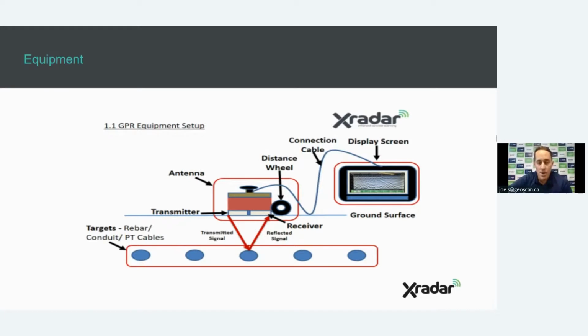Effectively, it works by the radar passing through the concrete, and as there's a change in material from concrete to, say, steel, such as reinforcing, it causes a reflection back up to the receiving antenna that displays that reflection on the screen. And so a trained technician is able to decipher between rebar, electrical conduits, radiant heating lines, and any other embedded object in the concrete.